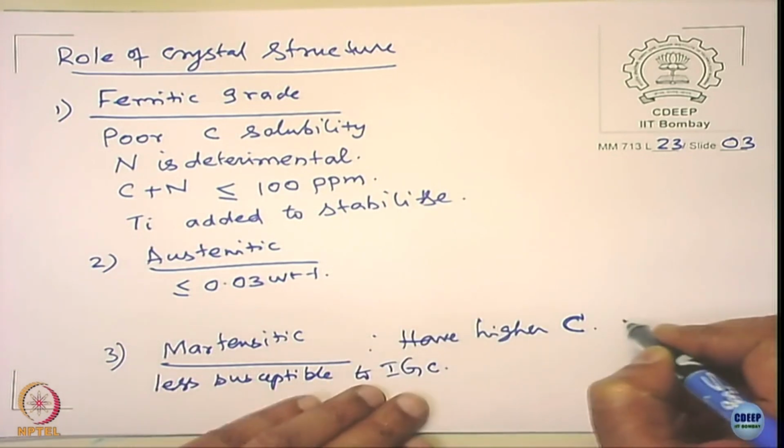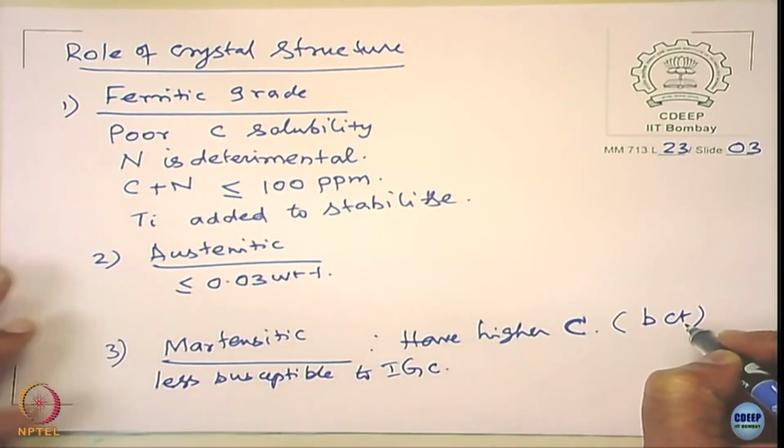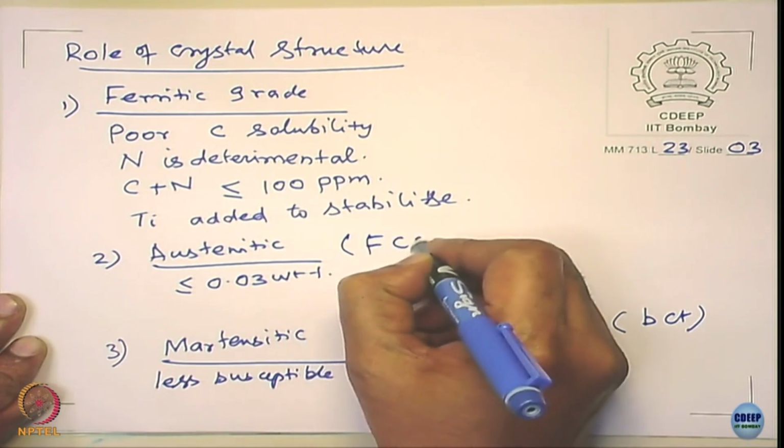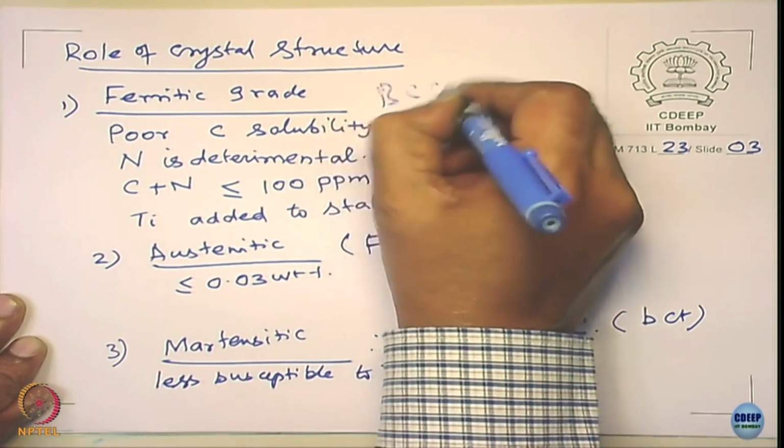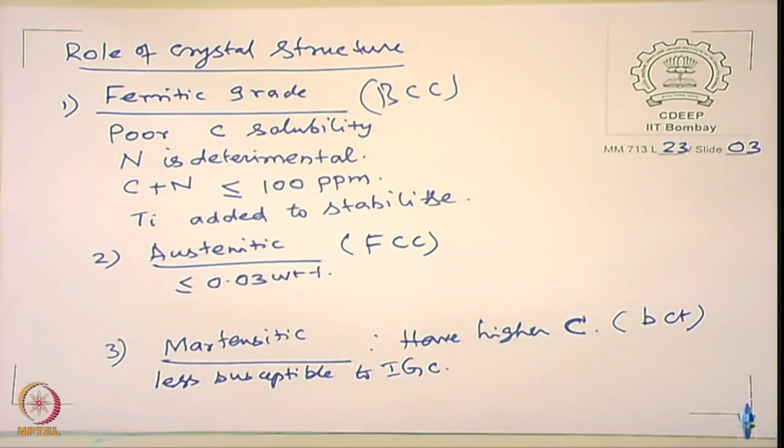When you take a martensitic steel and you solutionize it, take it to the austenitic region and then quench it, you form a martensite. When you temper it, how does the carbide form? The carbide forms within the martensite. What is the martensitic phase? It is actually a BCT, right? Martensite is a BCT structure. We saw it before, right? And this is the FCC structure, right? And this of course is a BCC structure. So it is a distorted lattice. So much of carbon is saturated now. Martensite is not a single phase. So when you heat it, it forms carbide. But how does the carbide form?